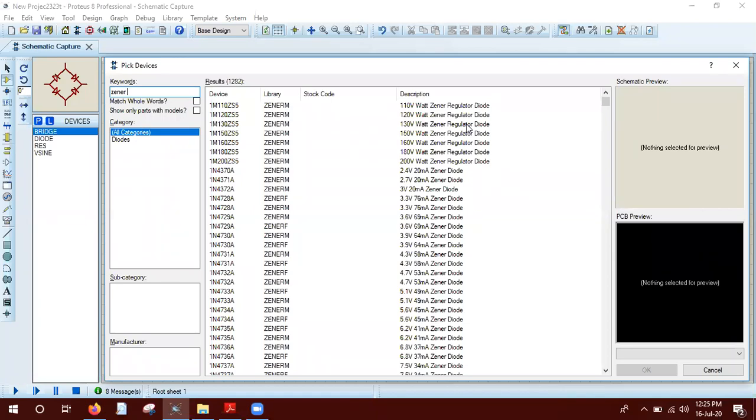So while choosing the Zener diode, there are 2 important factors that should be mentioned. One is, what is the Zener voltage? Because the Zener voltage means after that voltage, the Zener diode will enter the Zener region. And we all know that the Zener operation works in the reverse bias condition, and in the forward bias, the diode looks the same as the normal diode.